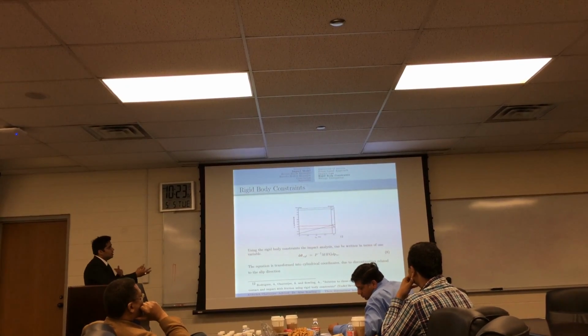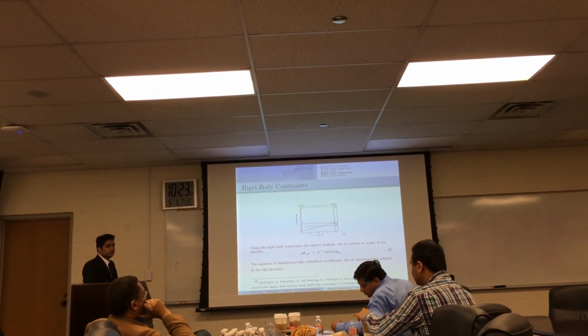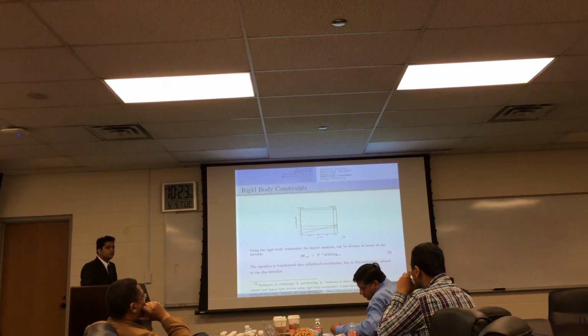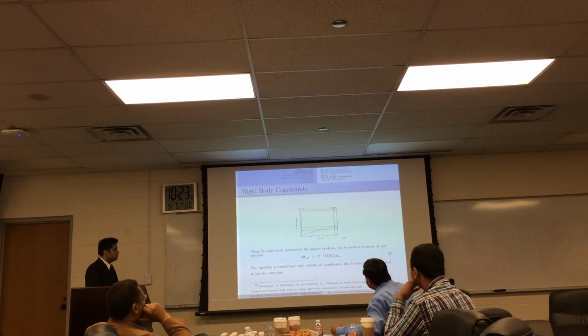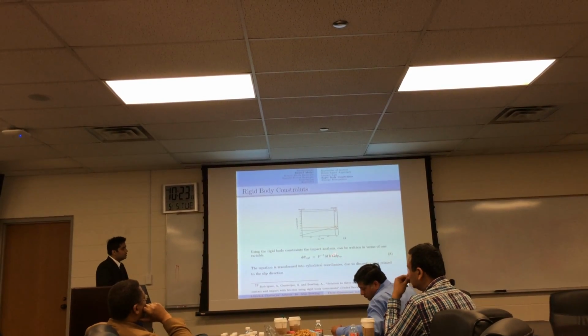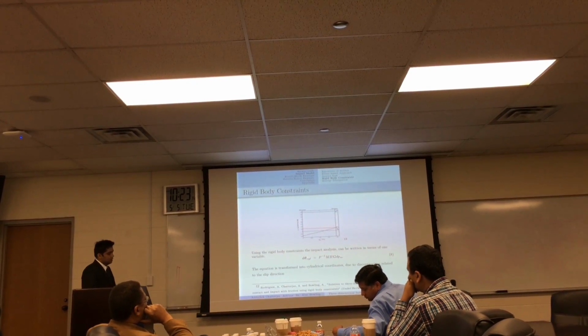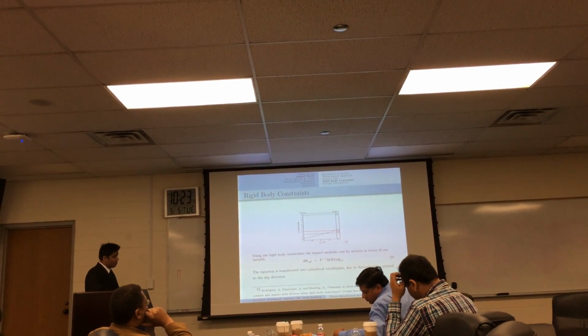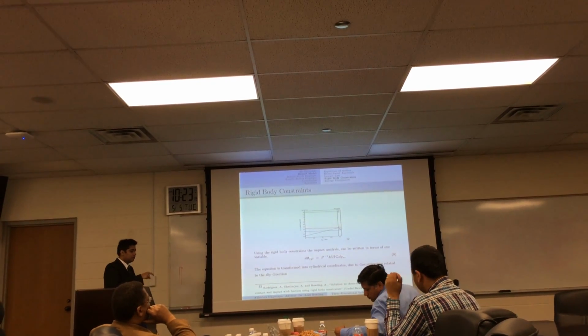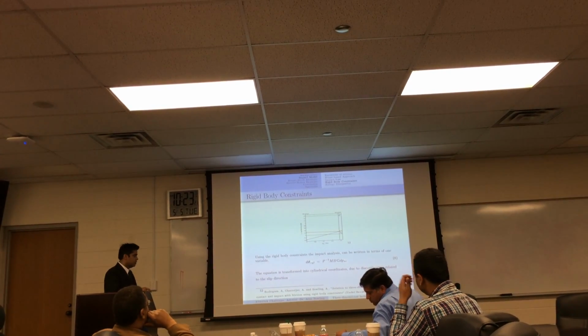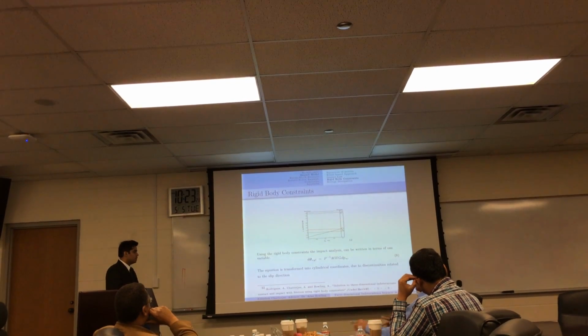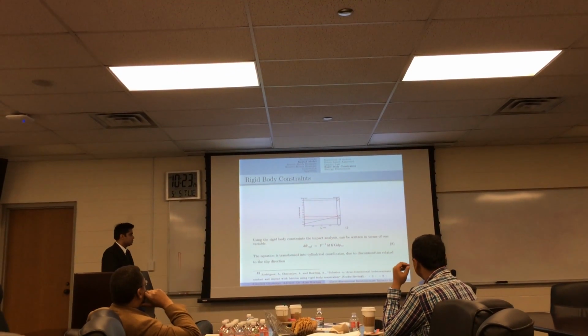And once we have the set of C_QRs, which are the rigid body constraint coefficients, we can put them all in a vector and describe all the velocities of the contact points in the system in terms of one independent variable, the impulse.